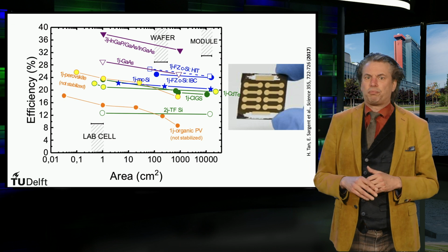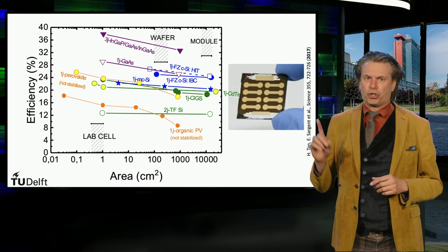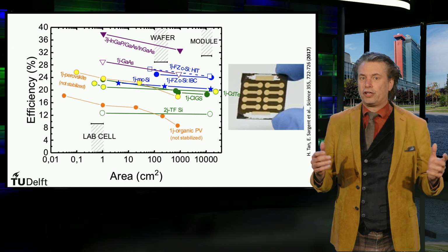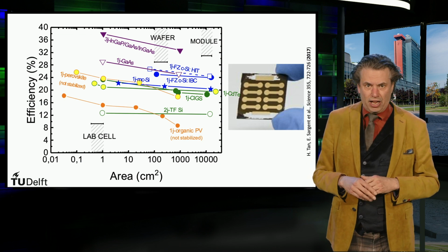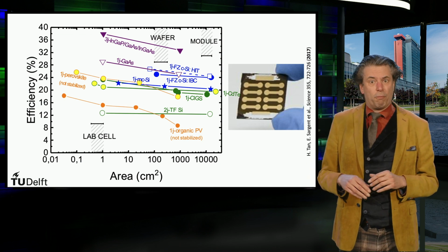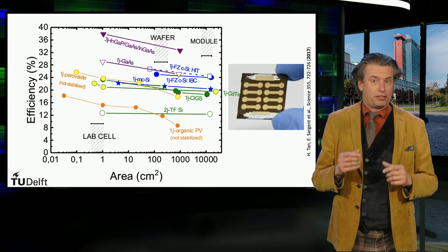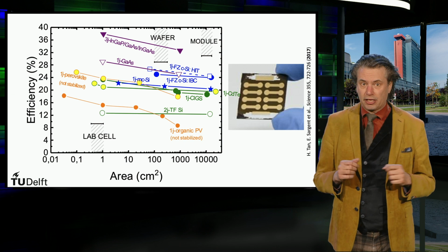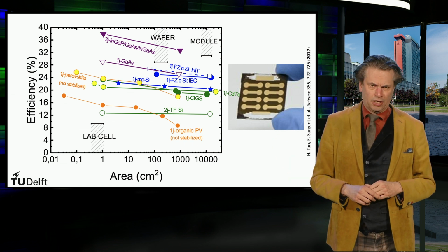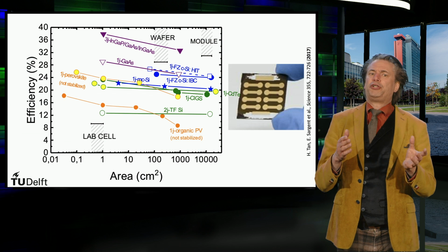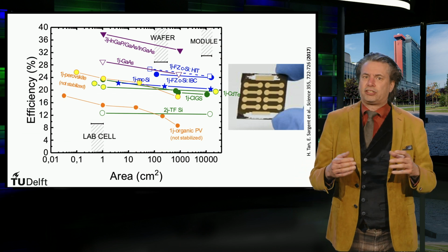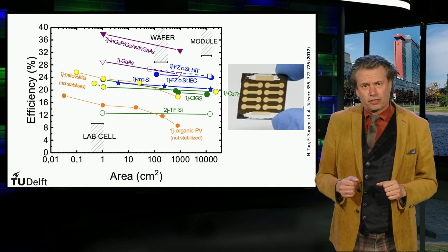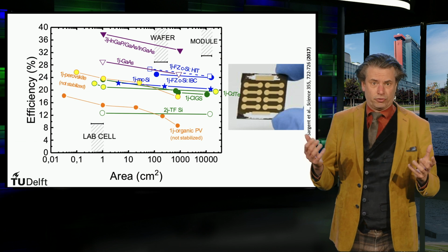The line corresponding to the perovskite technologies shows that this technology is not fully mature yet either. Record efficiencies above 25.7% for extremely small lab cells of 0.1 square centimeters have been obtained. The conversion efficiencies are reduced when the size of the perovskite cell is scaled up by a factor of 100 or even 1000.